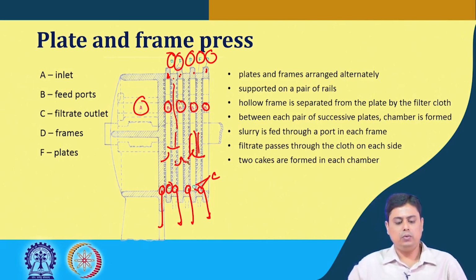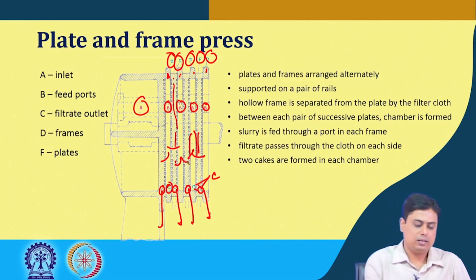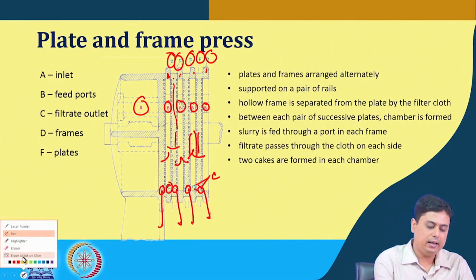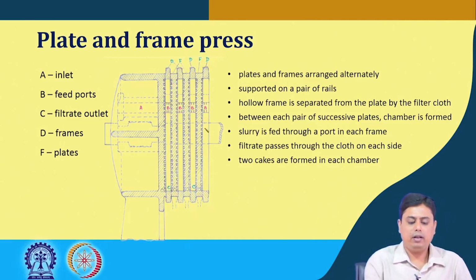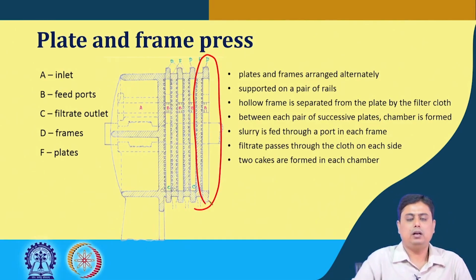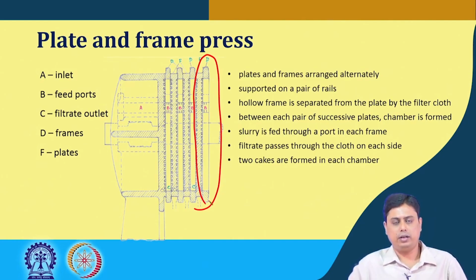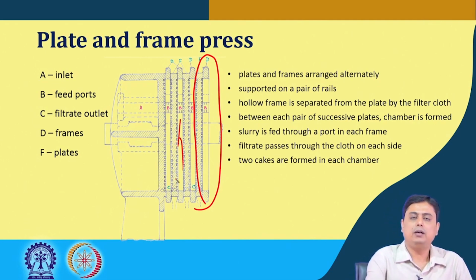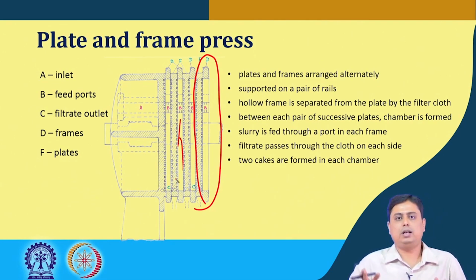The unique or the beneficial part of having such plate and frame arrangement is that each and every compartment can be taken out isolated. This can be isolated without disturbing the other arrangement. So when this filter media is now clogged with the cake formation that is coming from both the sides, and the cake has filled that chamber, this operation is stopped.